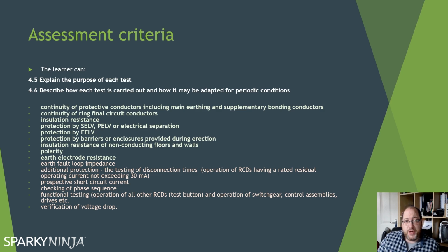SELV, PELV or electrical separation. You may not come across this one. This is where we've installed the protective measure of SELV and PELV or electrical separation instead of or as well as ADS. The main concern here is we have extra low voltage for the SELV and PELV, so we have to have them of a separate band voltage, band 1 from band 2. They must be segregated from LV unless they're wired to the same voltage. And with regards to SELV from PELV and SELV from LV, SELV is earth free, so we would not install a SELV system within an earthed containment because we need to keep it separated from earth. So you separate SELV from PELV, SELV from LV, and SELV from earth.